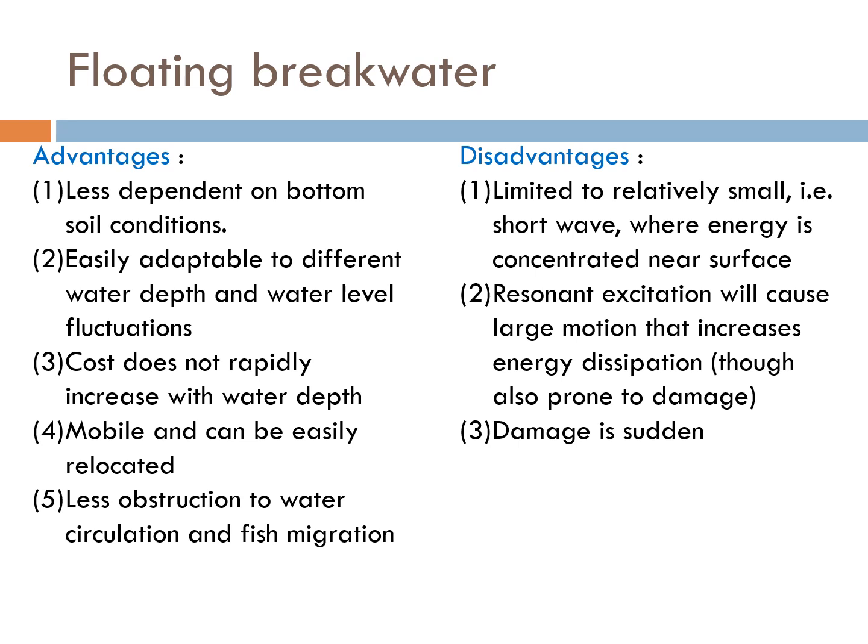Although this may mean that the wave can be more effectively dissipated or reflected in the process, it is also highly risky that during such excitation, the floating breakwater can be damaged suddenly when the cable snaps. This contrasts to massive coastal structures which are constructed on the sea foundation, whereby their damage is usually not sudden but gradual.